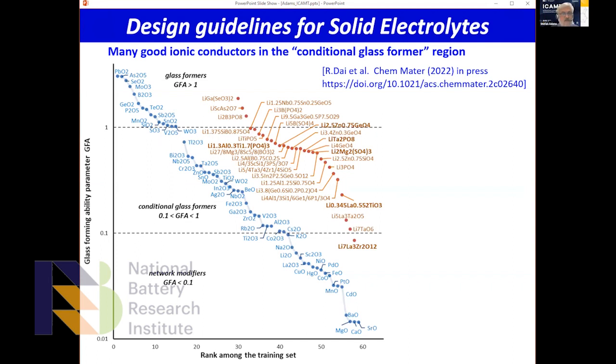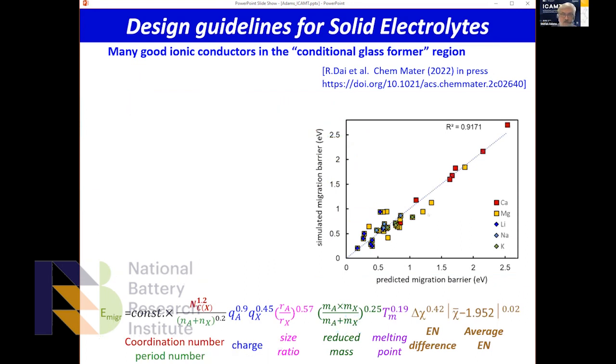The same factors, low coordination number, high charge cations, building stable blocks that have free space around them to move around, are really also the same things that help ionic conductivity. So we can use that to design new materials. For example, we will look in a minute at lithium tantalum phosphate as one such new material.